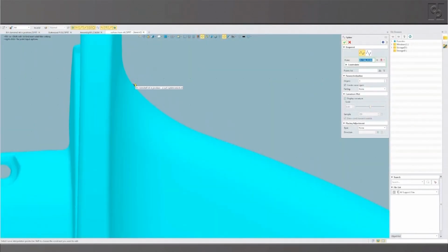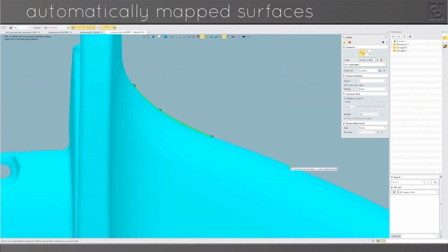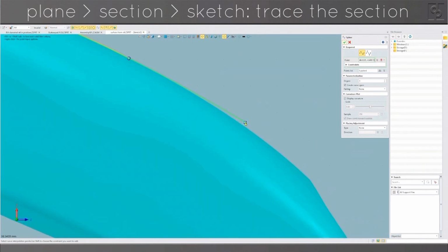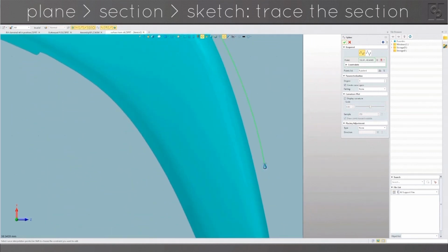So far we've looked at rectangular and fairly simple extruded shapes. What I'm doing here is something a little bit more complex. This is one of the handle surfaces, and I'm using a facility in my CAD system which is similar to Geometric Essentials, which claims to be able to project a surface onto a point cloud.